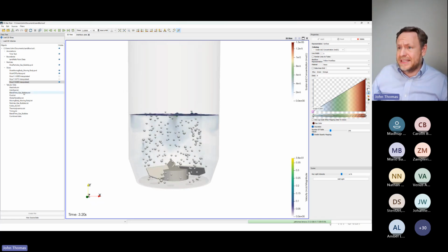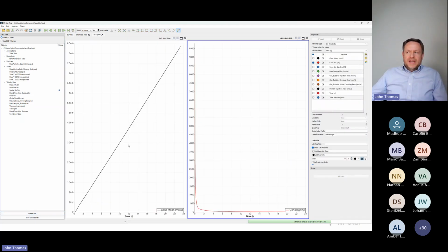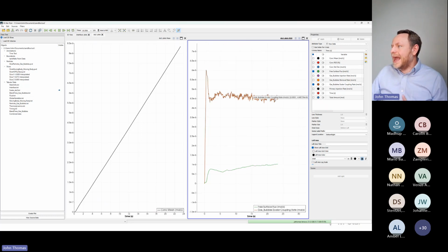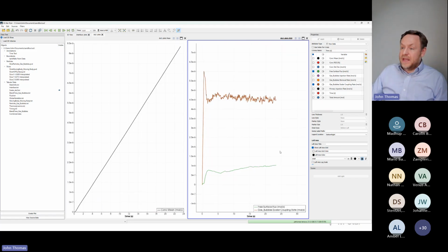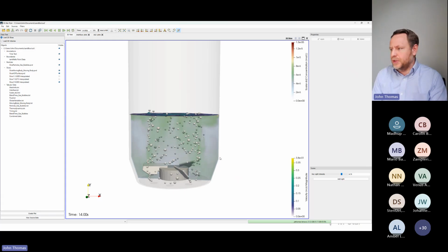And so if I go in here and look at my DO concentration, my scalar DO, this can't discriminate between the two. It just sees the two pathways, unless, of course, I actually look at this and see what my free flux is in moles per second and what my scalar coupling rate is in moles per second. Then I can begin to compare these more empirically. This was the higher impeller speed case. Here I see that for every, let's say, 4.5 moles of oxygen coming in from the bubbles, I'm getting about 1 mole from the headspace. Not nothing, as it were. As I watch this, you can see the oxygen accumulate and begin to deconvolve those two.